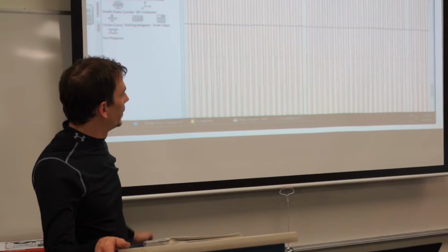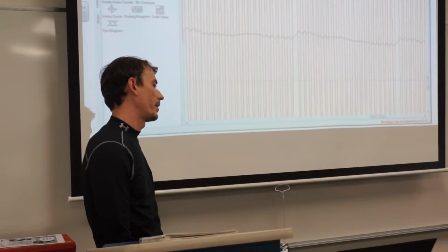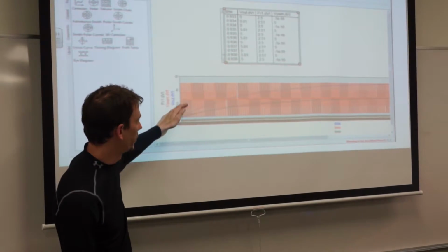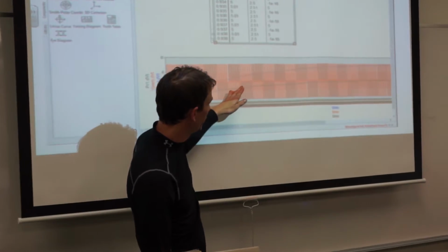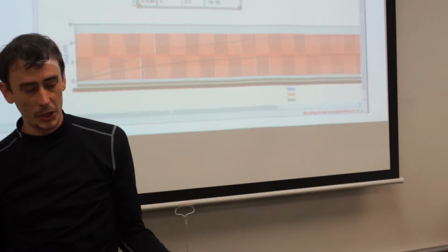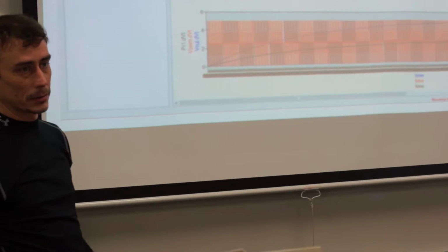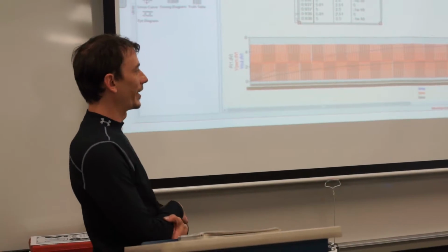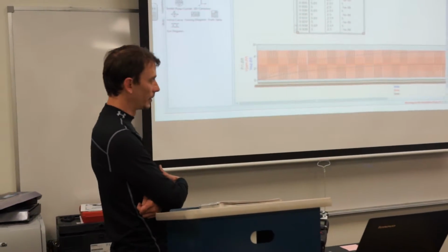The compromise to that is it's going to take time. If we start off, can you go back to that first one? No? We're starting off at 0 here. System start, you can see in this example how long it takes to achieve our desired voltage. Depending on the application of what you're trying to control the voltage of, that may or may not be acceptable. Some things you have time to wait. Other things you need an instant reaction. So looking at this, it was probably going to be something simpler like a motor speed control or maybe a light dimmer.